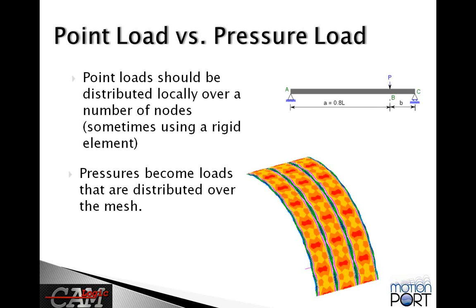If you have one component acting on another, that may be at a point, like at a joint. Loads like different fluid type pressures, hydraulic pressures, wind pressures for a structure, any of those things can be pressure loads, which are then distributed. And the distribution can be defined as an even distribution, or you can define some sort of function, or you can just input like a spreadsheet worth of data to define that pressure load.